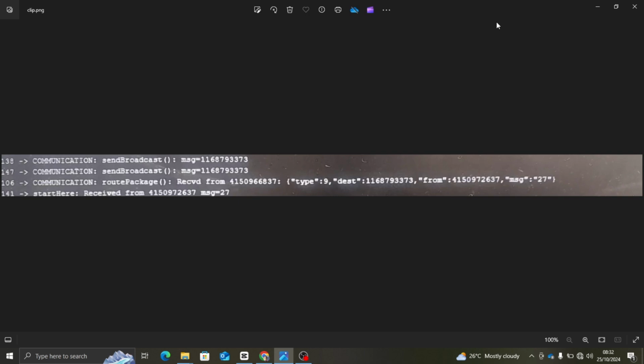So the first thing that happens is that the router device broadcasts its ID to all the devices in the network. When all the devices receive this ID, they know who to send their temperature to. They know who the router is. Each device in the network has a unique ID that can be used to identify it. As I said earlier, the router broadcasts this ID to the whole network so every device in the network can see it. When they receive this ID, they know, oh, I found the router ID. They then send their temperature reading straight to the router.